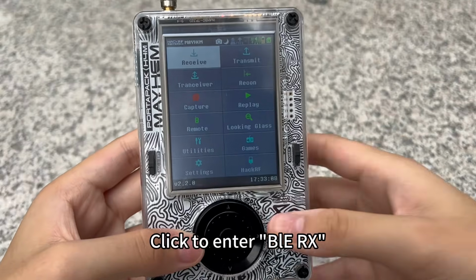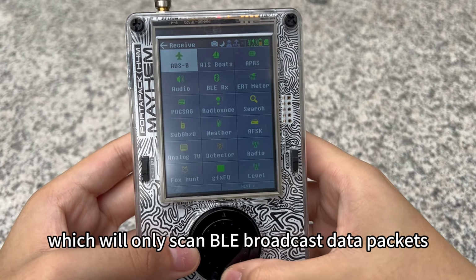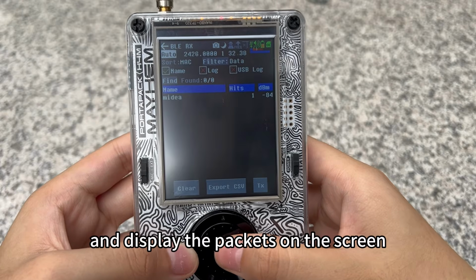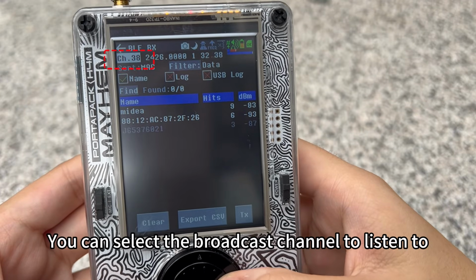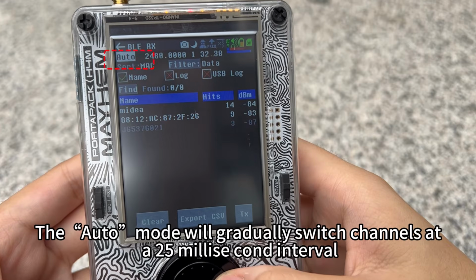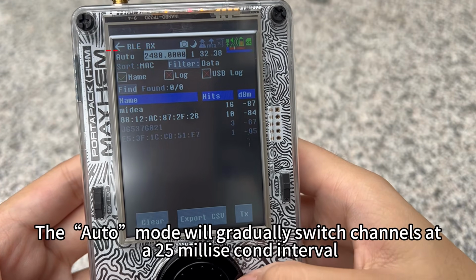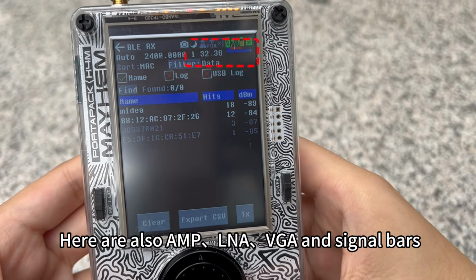BLERX. Click to enter BLERX, which will only scan BLE broadcast data packets and display the packets on the screen. You can select the broadcast channel to listen to. The auto mode will gradually switch channels at a 25 millisecond interval. Here are also AMP, LNA, VGA, and signal bars.